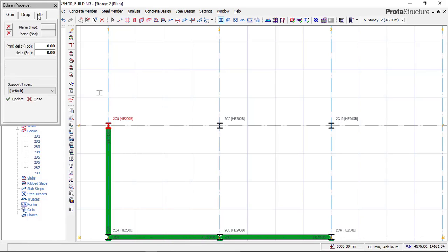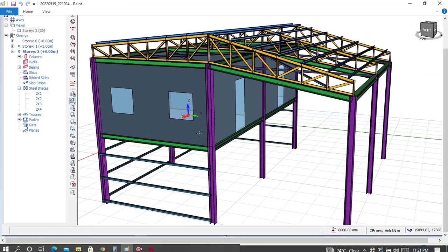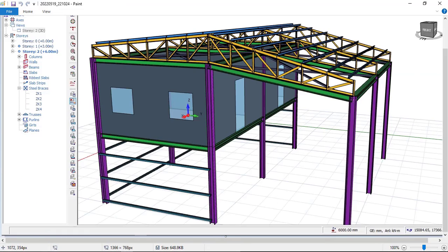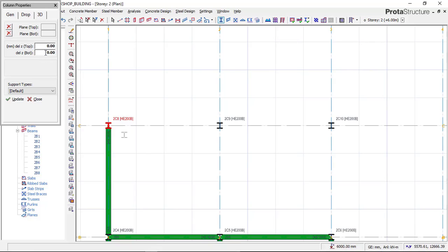We'll click on 3D, and then we want the top to drop, because looking at this phase right now, you can see that what is dropping here is the top, so that we can have this inclined plane. So we click back on our footer and then click on this Z top as minus 800. That is what that column is dropping with.